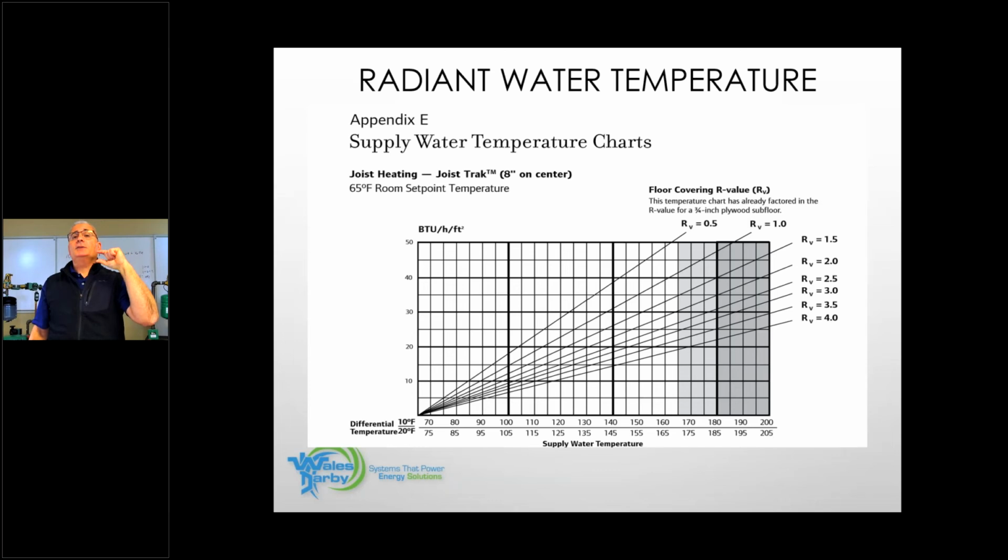That is critical because we end up heating by convection that way. If I push the insulation all the way up against the tubing in the subfloor, it's never going to work, because now I'm not creating that convection underneath, not heating the subfloor, which ends up heating the room. That's why if you tell me, hey Jim, we're going to do radiant, it's going to be primary, and just put the tubing under the floor, no plates, I'm going to grill you till the cows come home to make sure that you're on the job, and to make sure they insulate it properly.